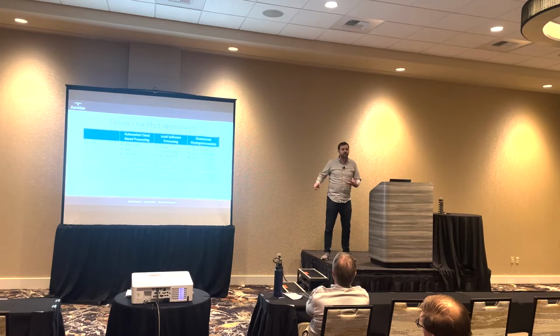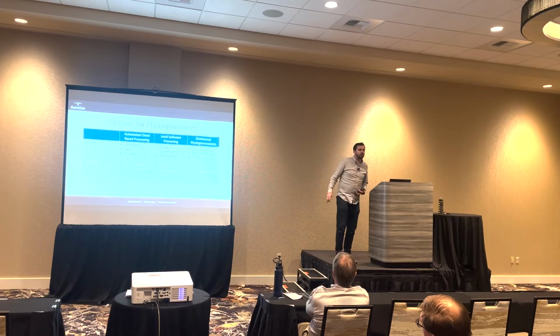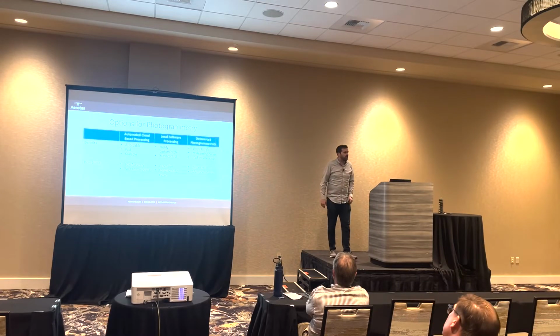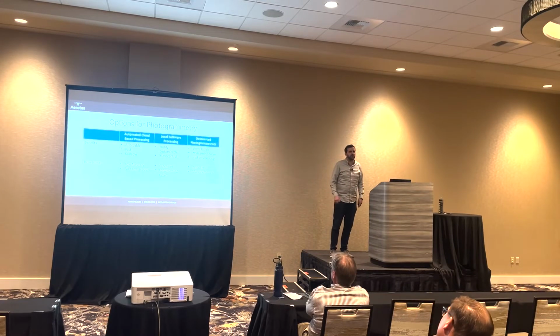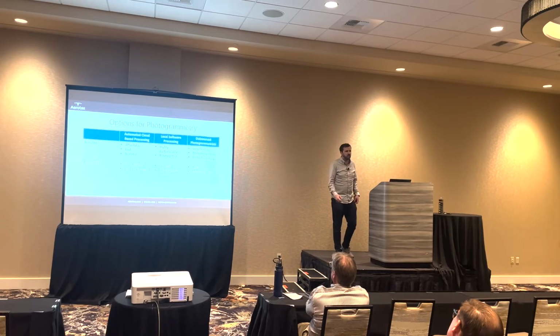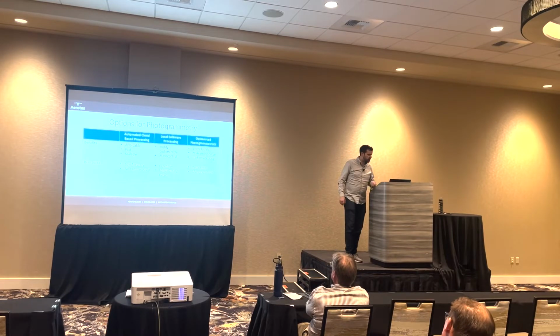They're very good for a lot of GIS applications where you just need an orthophoto and you can have a couple of feet worth of georeferencing slop. But for surveyors, where especially if you're doing topo and you need your vertical accuracy to be 1/10 of a foot or better, we strongly discourage those.